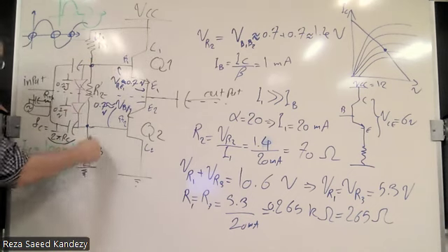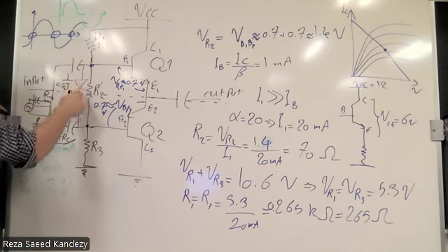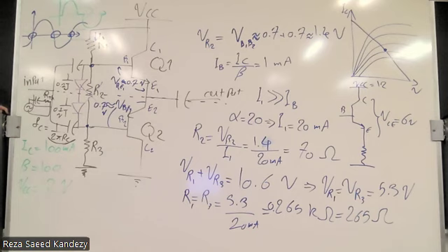This is the circuit, correct? So these are both in forward bias. We talked about the constant drop model when we talked about the diode. We said if we have a forward biased diode, we can simply replace it with a single constant voltage drop, which for silicon-based diodes is 0.7. For germanium it was 0.3.